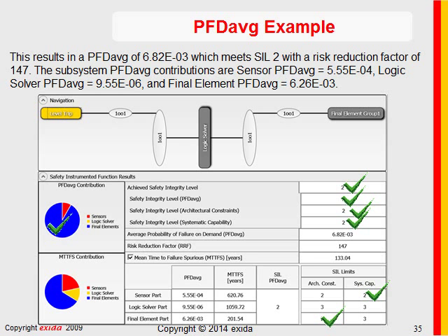Overall, this has a pretty low false trip rate, 1 in 133 years. Now, that sounds pretty good, but if you have 10 functions, it's 1 every 13 years. If you have 100 functions, it's 1 every 1.3 years. Keep in mind, you really do need a high number to avoid costly false trips.